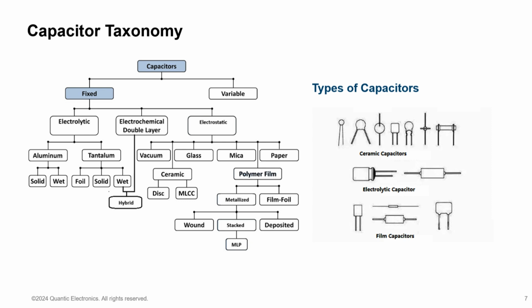Supercapacitors have very low breakdown voltages and are restricted to low voltage applications, typically below 10 volts. The low charge and discharge rates compared to other capacitor technology mean that they're not suitable for many pulse or ripple applications. On this tree, we can also see an anomalous hybrid capacitor. It is actually possible to combine some pseudocapacitive elements with an electrolytic capacitor in some cases, and we'll be going into that a little bit further in the coming slides.